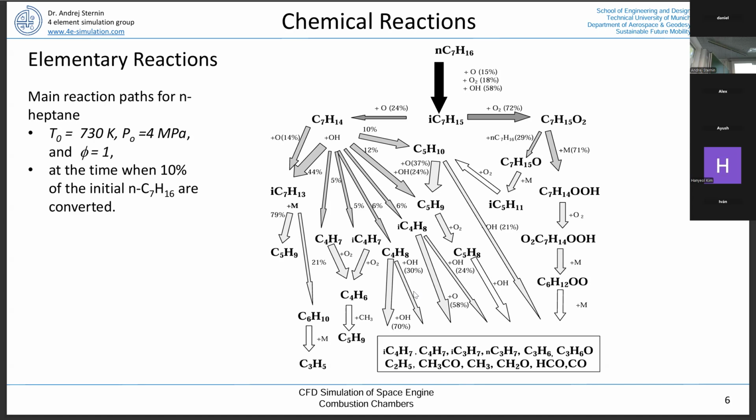So a detailed analysis of the individual elementary reactions helps us to find a way to control the combustion process by locally adding or changing the conditions for the chemical reaction to get favorable conditions. For instance, in aero engines, some of you may know that initially we burn fuel rich in order to have the ignition, the flame, to avoid flame out. But fuel rich is something we do not want, because that would increase the fuel consumption.